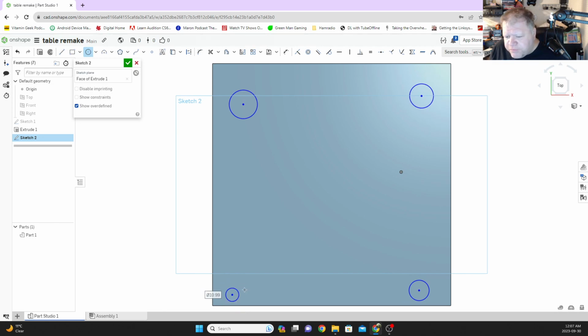So that's a little small, but I will do. Okay, so there, as you can see, they're not really lined up anywhere. They're just all over the place. So what I'm going to do is use my dimension tools, and I'm going to bring the circle up to here, and I am going to make it only 15 millimeters up.